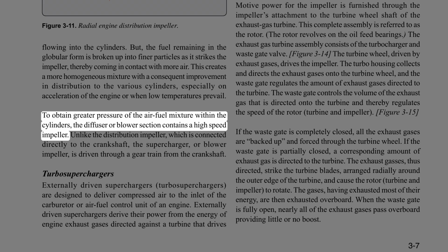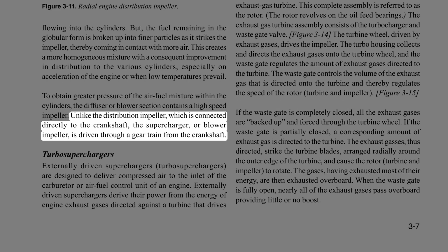To obtain greater pressure of the air-fuel mixture within the cylinders, the diffuser or blower section contains a high-speed impeller. Unlike the distribution impeller, which is connected directly to the crankshaft, the supercharger, or blower impeller, is driven through a gear train from the crankshaft.